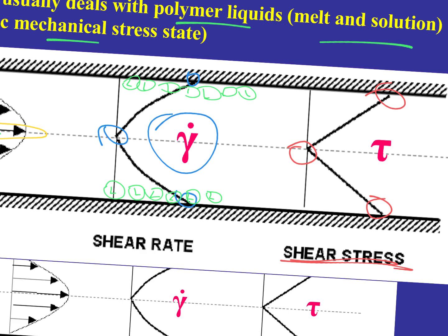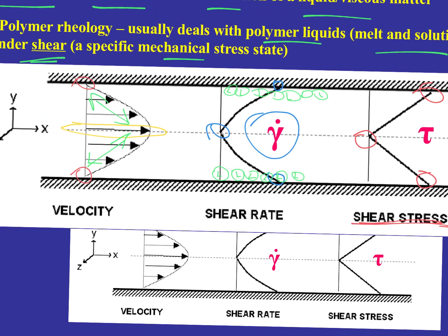And so that makes these values smaller, and then it means that these values of velocity are going to go up in the presence of that lubricant. All right, so we try to free the polymer chains that would normally be at 0 to something that's greater than 0 due to the presence of this lubricant on the walls. All right, so now you should see why these lubricants are so important, because they make this possible.